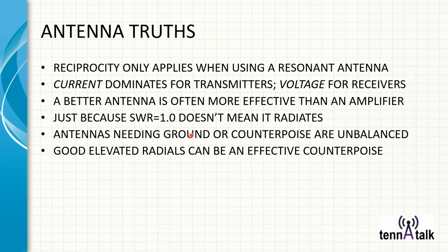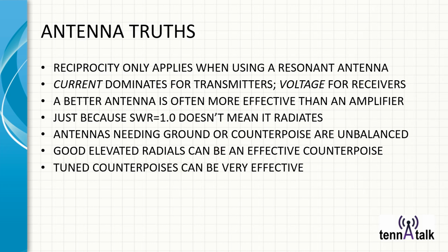As few as 2 radials as an elevated radial, but better yet more radials, makes a pretty darn good counterpoise, and some classic antennas have been designed with elevated radials. A tuned counterpoise can be very effective. I found this out very recently for people working totally portable, walking about or even bicycling around, that they drag a long counterpoise wire behind them that they tune separately from the vertical whip. And it can make a huge difference, which you can hear on the receive side.